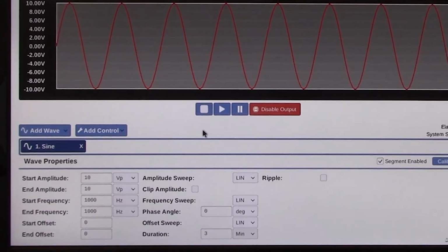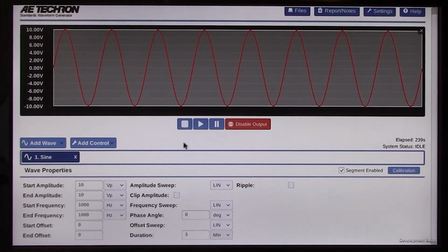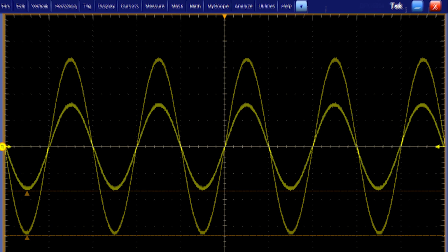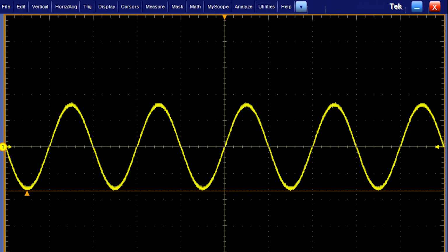Now let's go ahead and make sure everything's connected. We do have our oscilloscope hooked up to the output of the 7234. And let's go ahead and run our first pulse with a gain set of 100% on our 7234. Okay, excellent. Perfect. The pulse is roughly 10 volts peak. All right. Now let's go ahead and adjust the gain to roughly 50% and take a look at the pulse. We are expecting a 5 volts peak. All right, perfect. That looks good as well.